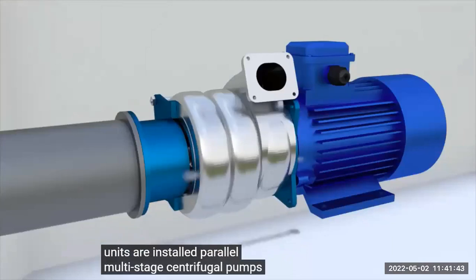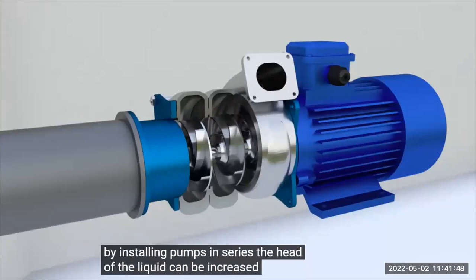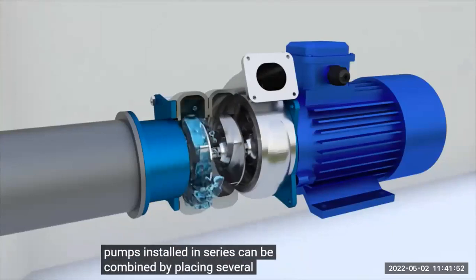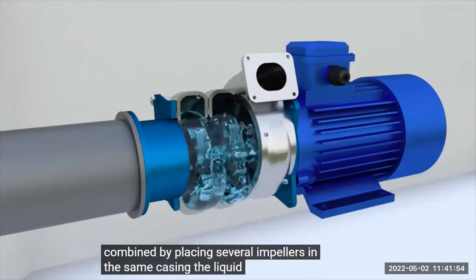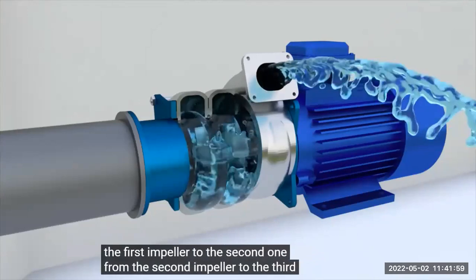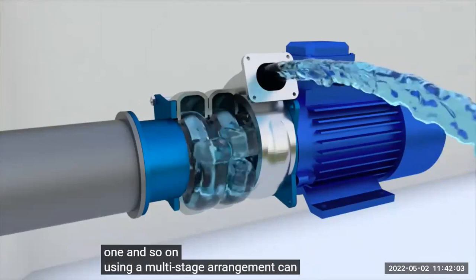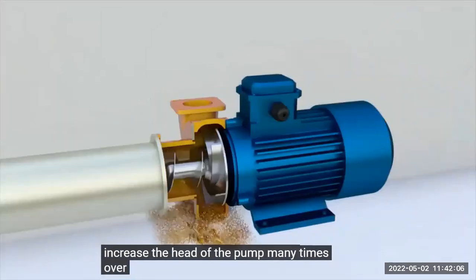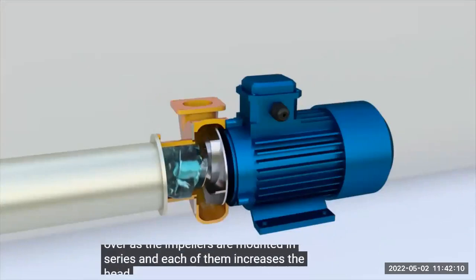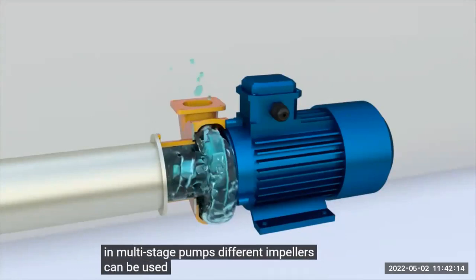Multi-stage centrifugal pumps. By installing pumps in series, the head of the liquid can be increased in the system. Pumps installed in series can be combined by placing several impellers in the same casing. The liquid will go from the first impeller to the second one, from the second impeller to the third one, and so on. Using a multi-stage arrangement can increase the head of the pump many times over, as the impellers are mounted in series, and each of them increases the head. In multi-stage pumps, different impellers can be used.